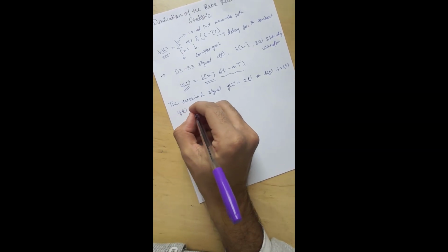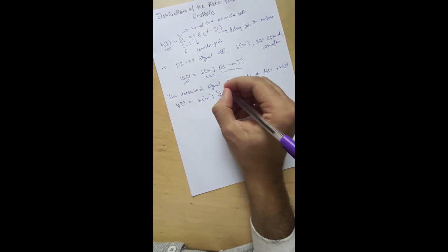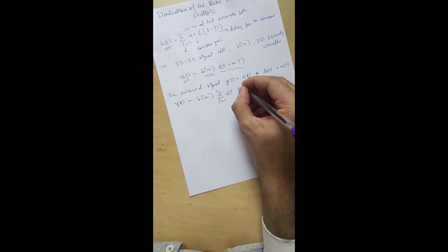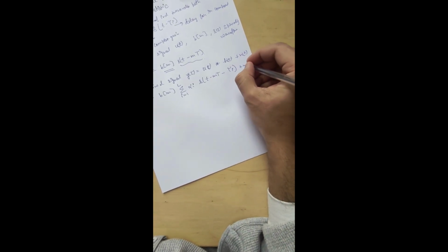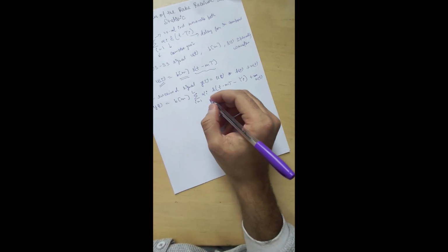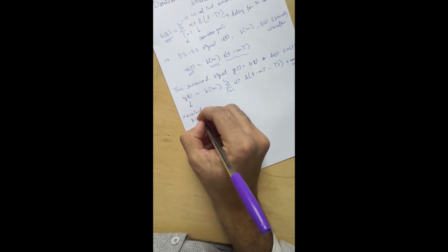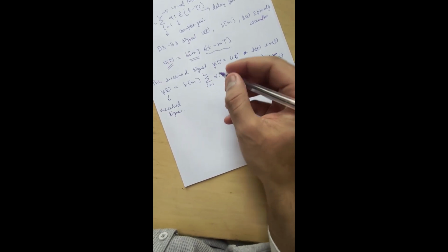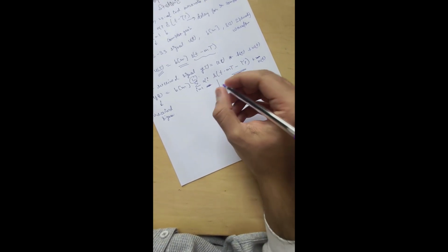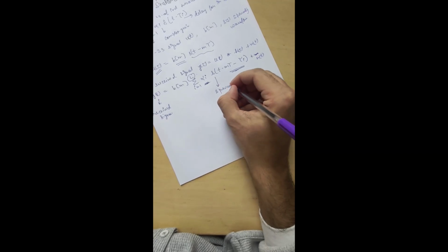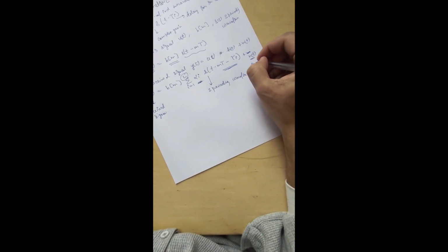Writing it out completely, we get the received signal y(t) as the sum of L delayed and scaled versions of our spreading waveform s(t), plus obviously the AWGN.